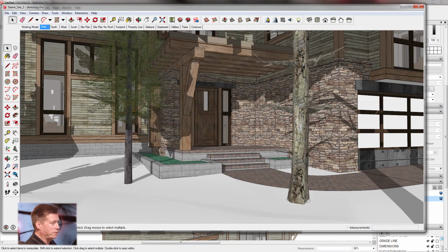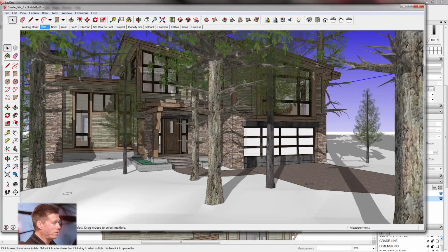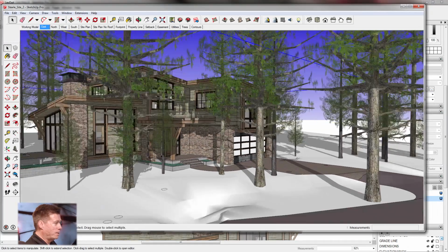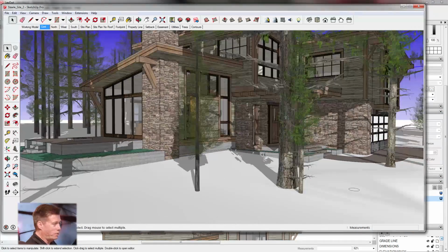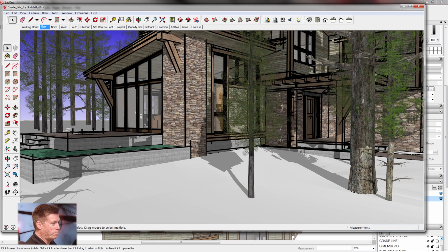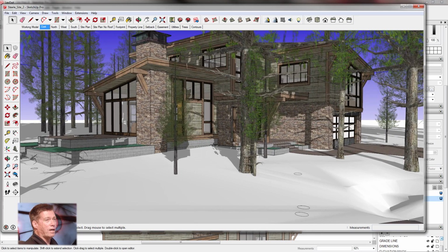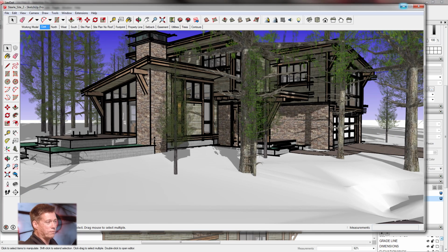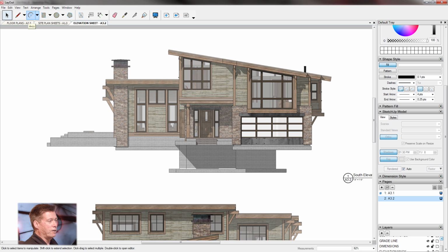So, I'm a couple down here on the board form concrete. I can see how much of the board form concrete is exposed here. I've got 1, 2, 3, 4 boards. So I know I can get it exact, or at least close enough for setting a grade line.